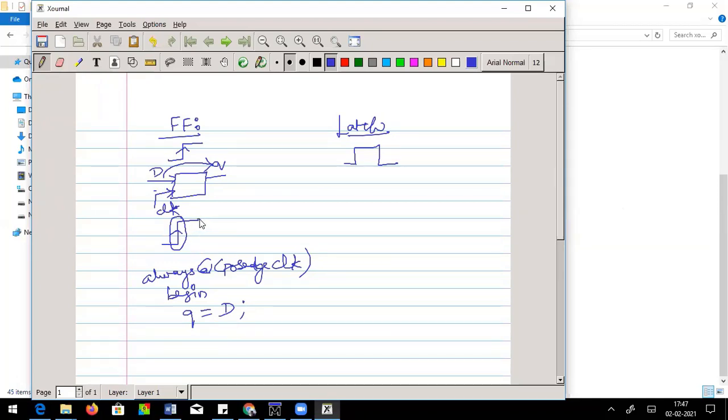Remember, after this, it will retain whatever has been captured at that moment till the next clock cycle. The value changes in Q only for the next clock cycle. It will again look at D. If anything is new, it will get sampled. Else, it retains the same value. Even if D doesn't change, that value gets sampled and given as my output. The point here is, as far as D flip flop is concerned, it is sensitive only to this fraction of time interval.